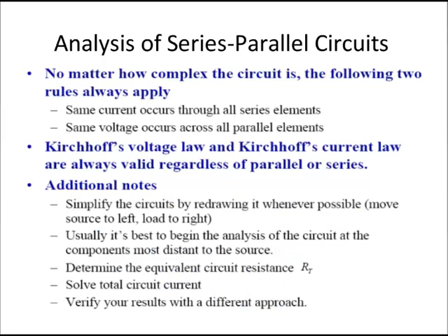So whenever we analyze a series parallel circuit to find out, say for example, VR3 or IR4 or the power in a certain branch, there's a couple of things that we should always remember. No matter how complex the circuit is, the same current will always flow through series elements, and the same voltage will be across all of the parallel elements.